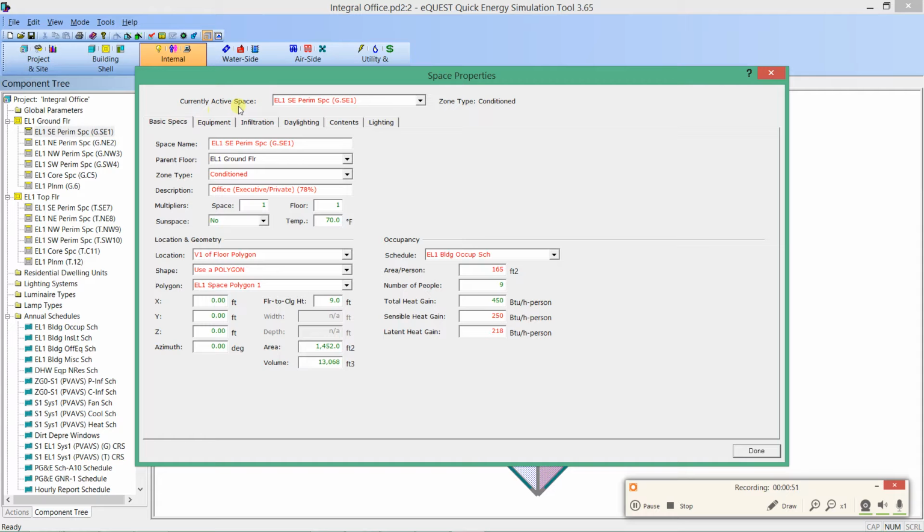So for this space, we can actually see this space has many different tabs of properties associated with it. Everything red has been defined by the wizard mode or some format of this project. Essentially, red indicates where the user has made an input. And even if you specifically haven't set 250 BTUs a person, another input we specified picked that for this input.